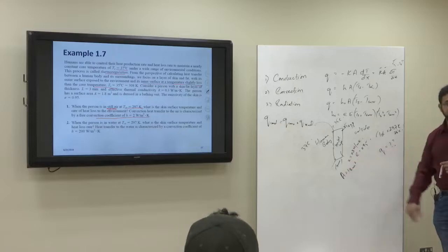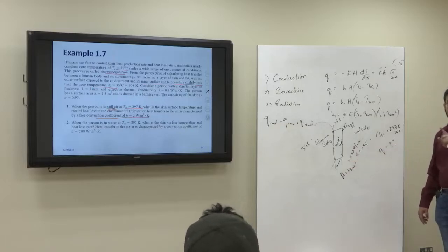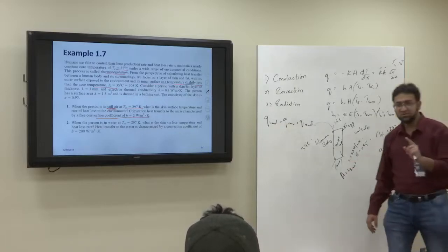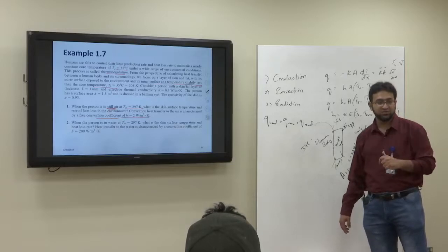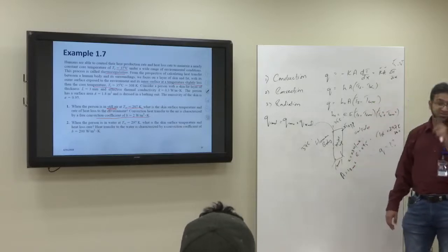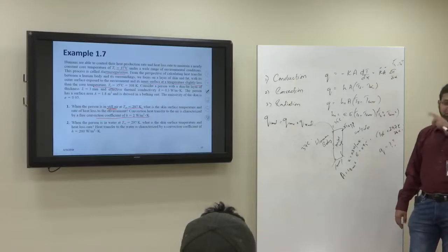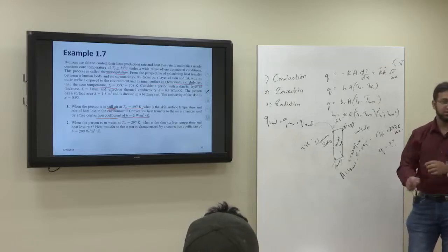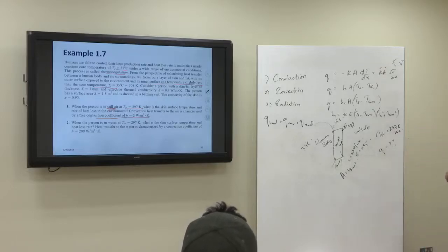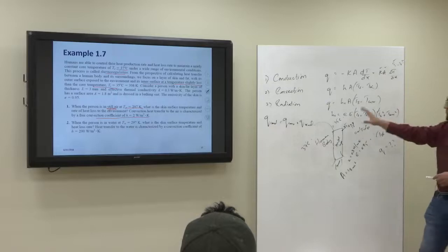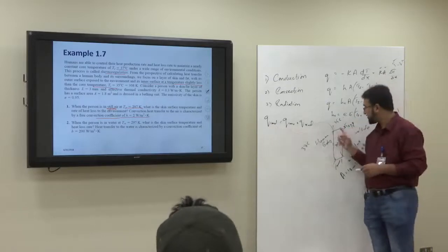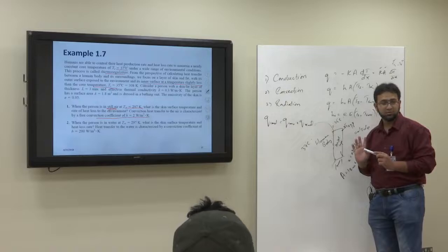This is the thickness, 3 millimeter. Remember, use only the basic SI units. So 3 millimeter converted into meter. This was the same case in the last problem as well. I forgot to mention, you were given value in megawatt, so you convert it into watt. Okay. Anyways, so you get this Q conduction. Only Ts, skin, unknown. Okay.